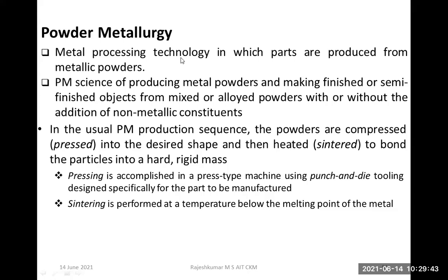Especially in case of powder metallurgy, it offers flexibility and the minimization of segregation. Segregation means the different parts get segregated easily, so that will be minimized. And here the flexibility can be easily achieved. Here we can obtain different graded microstructures just by varying the physical and mechanical properties of the materials. This powder metallurgy offers advantages over ingot metallurgy.